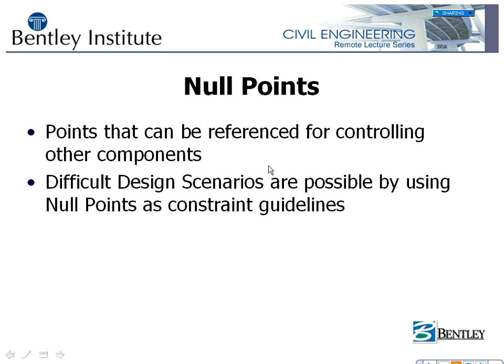Next item coming up is null points. Null points are points that can be referenced for controlling other components, or component points. These are like the phantom pivot points in superelevation in the previous versions of InRoads. These are points that don't have to be used other than for referencing purposes. Difficult design scenarios can be solved using these null points as constraint guidelines.